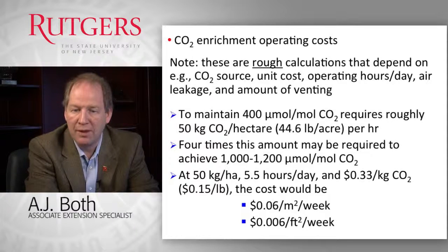How many hours do you operate it? How much does the greenhouse leak in terms of air leakage to the outside environment? And how much ventilation do you do? How much air exchange do you do with the outside to maintain your temperature? Typically, when we do CO2 enrichment, we stop CO2 enrichment when the ventilation rate reaches a certain threshold. So a little bit of ventilation is typically acceptable when we start enriching, but at a certain rate of ventilation, it doesn't pay to add CO2 because most of it will be expelled immediately with the ventilation we are trying to impose to maintain temperature set points.